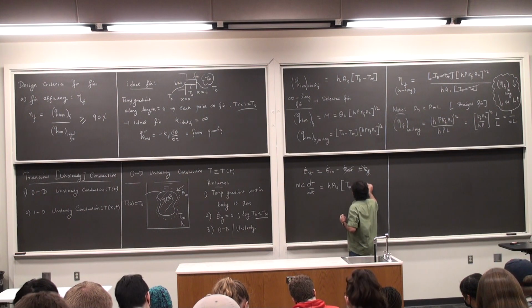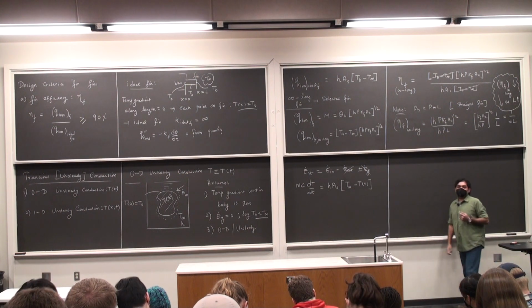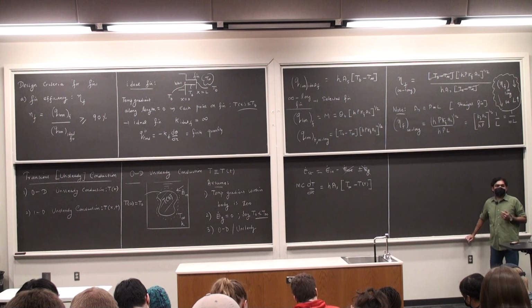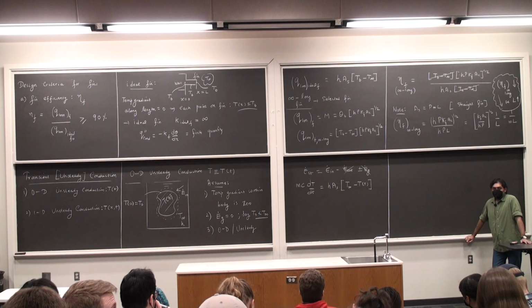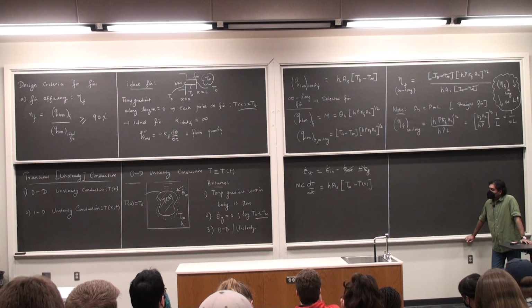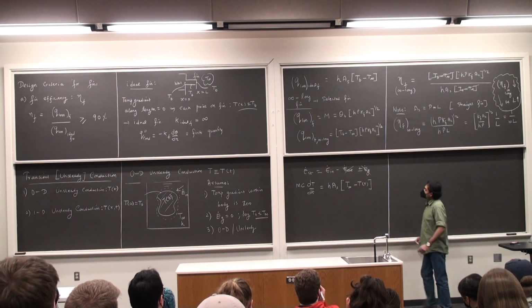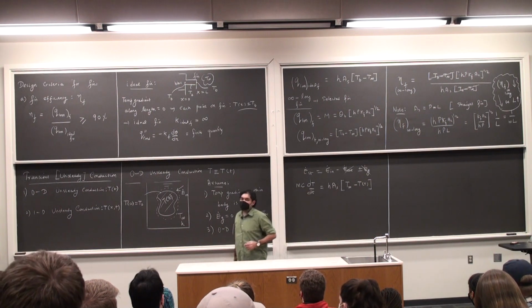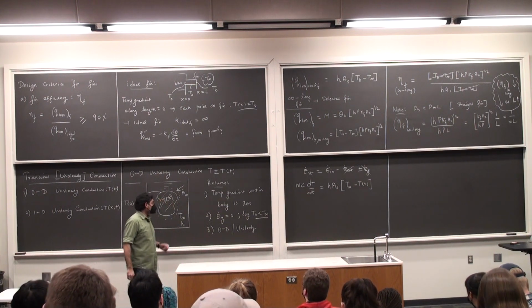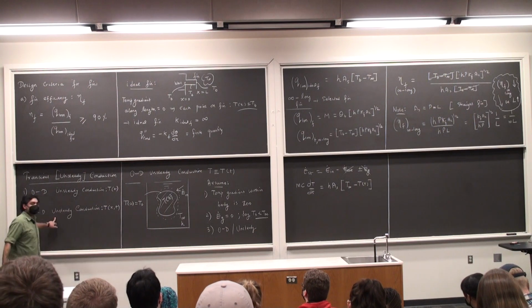So you see that this is the situation. Does this make sense to everybody? Yes. So normally would the E dot stored be a partial derivative? E dot stored would normally be a partial derivative if there was a temperature gradient present within. Now there is no gradient present. So if I look at a problem of 1D unsteady conduction, that's going to be a partial derivative.